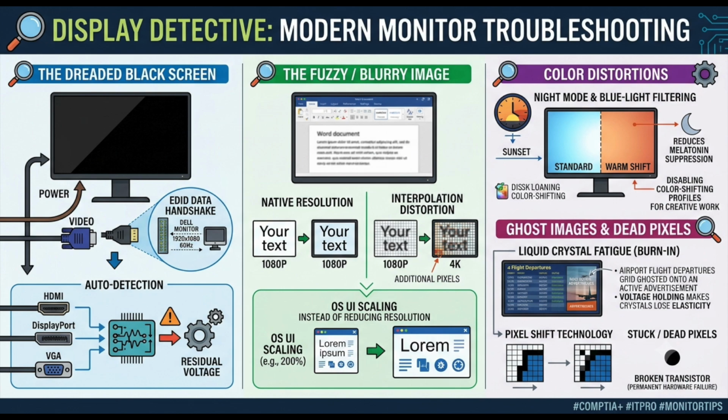It acts as an aggressive physical reset. By displaying pure white at maximum brightness, you are sending maximum voltage across the entire physical grid simultaneously. Okay. You are forcing every single liquid crystal to fully untwist to its absolute limit. Doing this continuously for several hours can sometimes generate enough mechanical action to flush out the stuck state, allowing the crystals to reset when the screen is finally turned off. It is essentially deep tissue massage for tired pixels. Deep tissue massage for pixels. I love that.